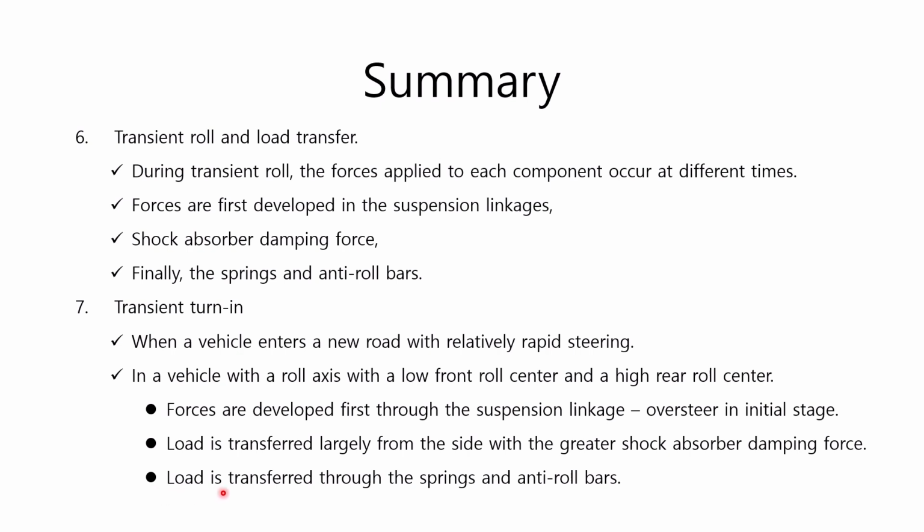Next, the loads are transferred from the springs and anti-roll bars. If the front wheel roll stiffness is high, understeer tendencies may appear at the maximum load transfer of transient turn-in.